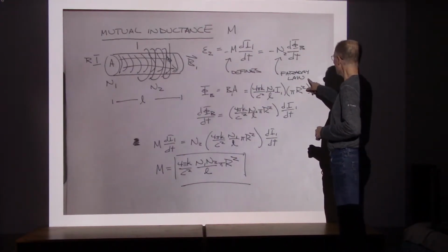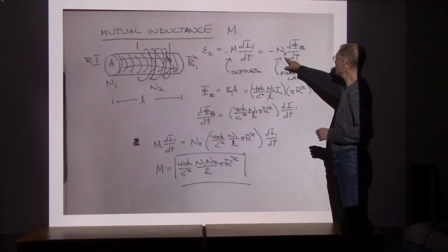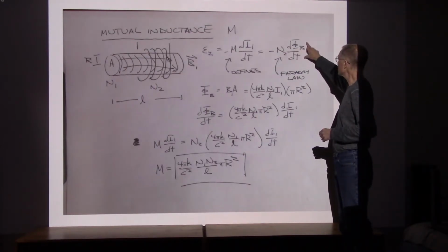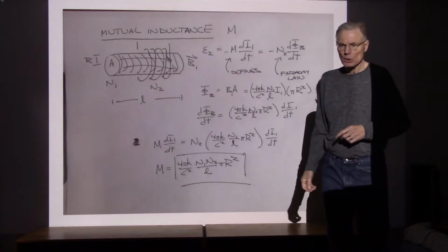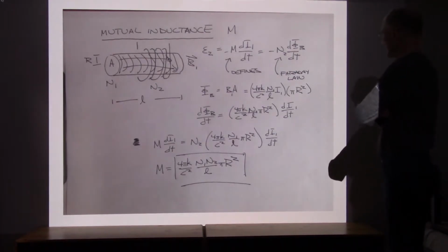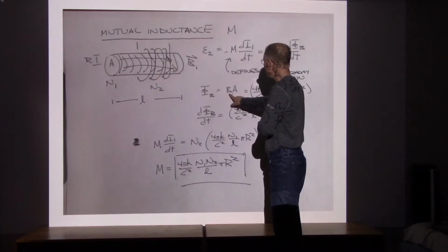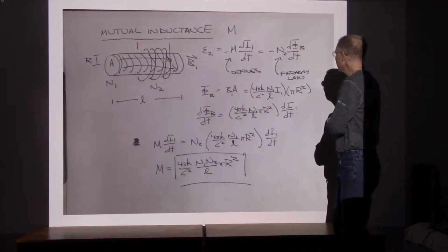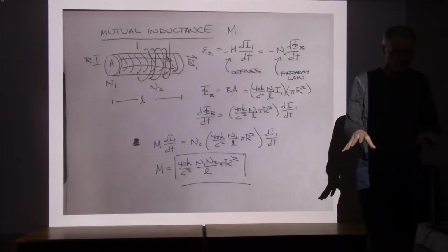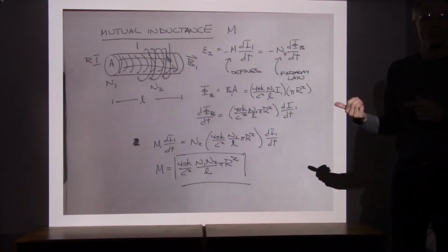Now from Faraday's law, the EMF that we get is going to be proportional to the number of loops times whatever the flux variation is here. All right, so we can go ahead and calculate that. The flux is going to be the magnetic field times the area, and the magnetic field for a solenoid, we're actually using our solenoid formulas for this example.